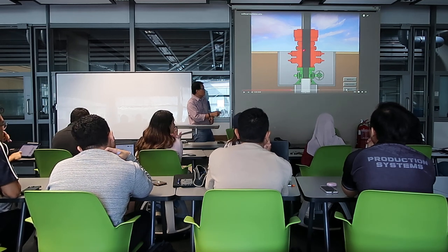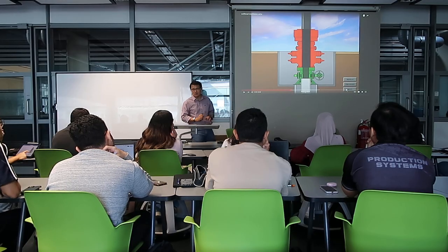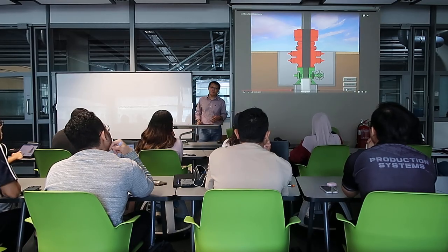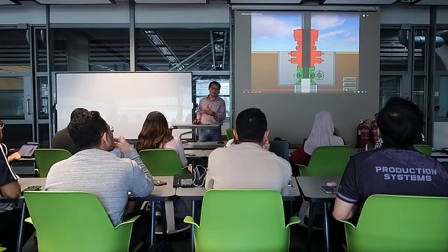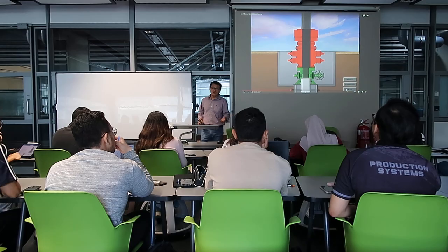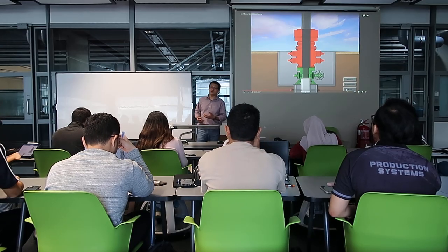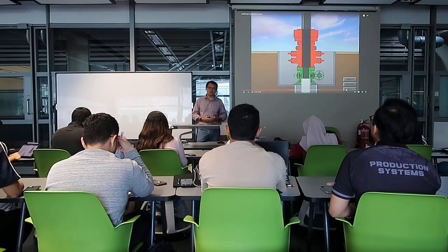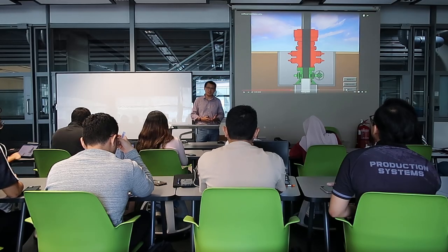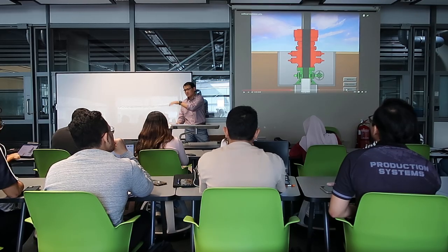But what normally now we do is BOP will do the full stack test offline. A full stack test can vary from like 4 or 5 hours to even 8 hours. So that's why now in most of the operations we request the rig to have offline testing capacity. So they basically will put a test stump down, they put the BOP there, they do the full RAM test.